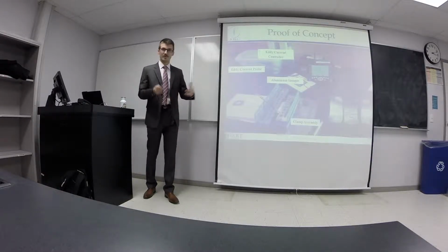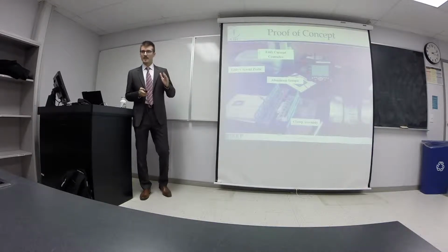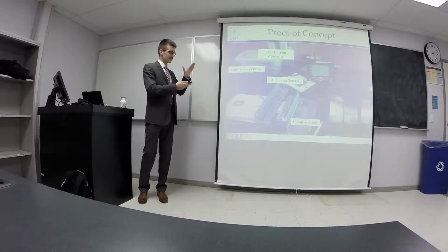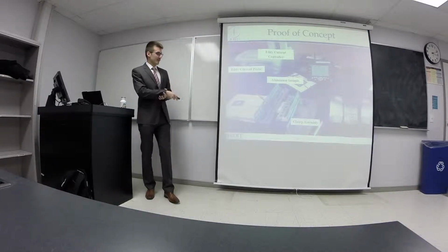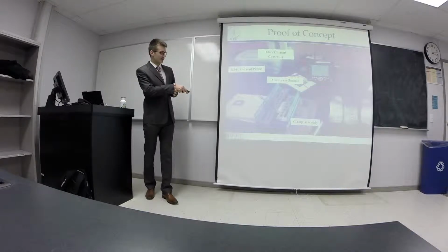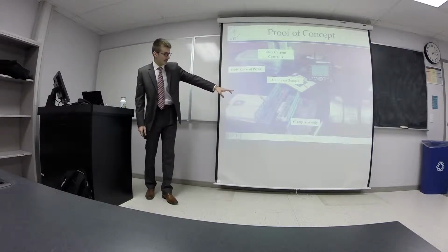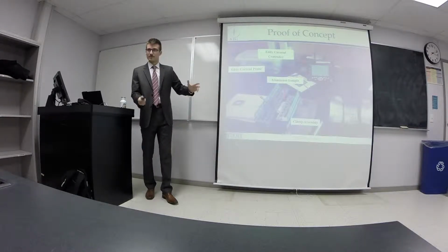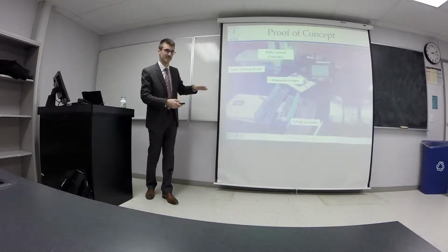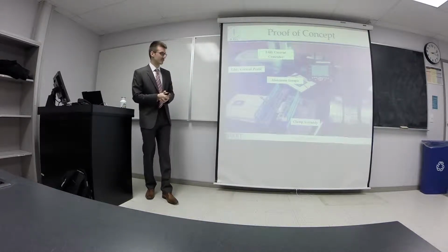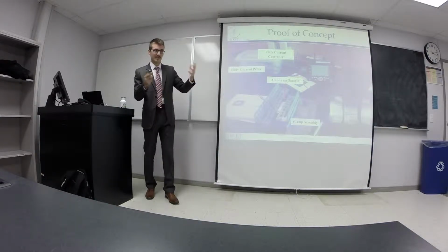So, proof of concept. Moving forward, I just wanted to see what measuring subsurface cracks would be like in this very basic model that I just showed. Here we have a little experiment. We have the eddy current probe on the left, the aluminum sample in the middle, the eddy current controller, and the clamp assembly itself. For those that were present in last year's presentation with my group, this was one of the basic clamp assemblies we used to hold a material in place. And blown up on the right is the actual sample itself, with the middle one being the one that has the flaw.